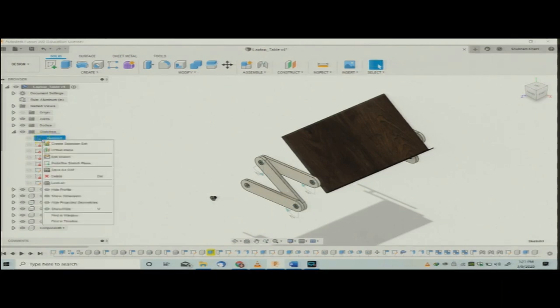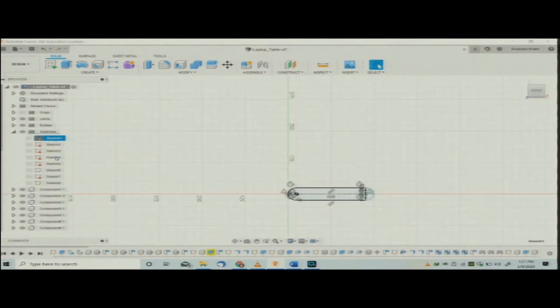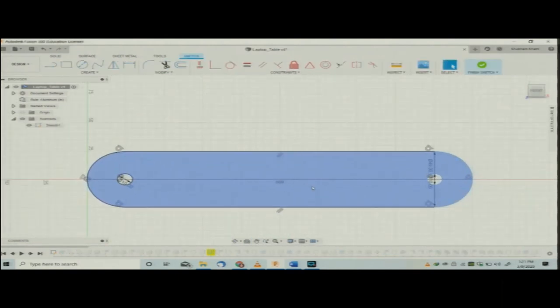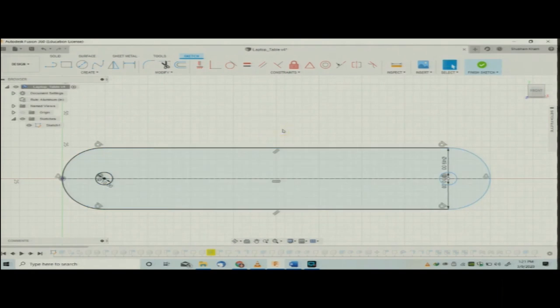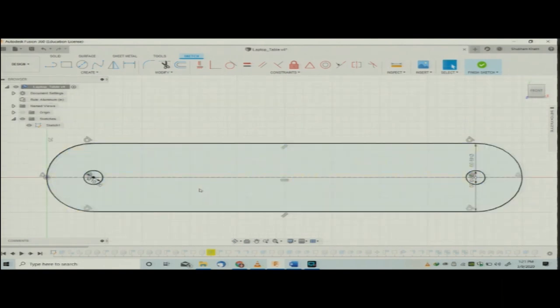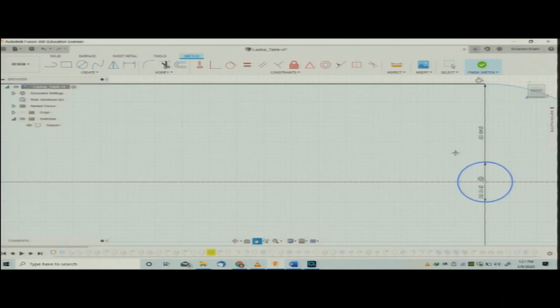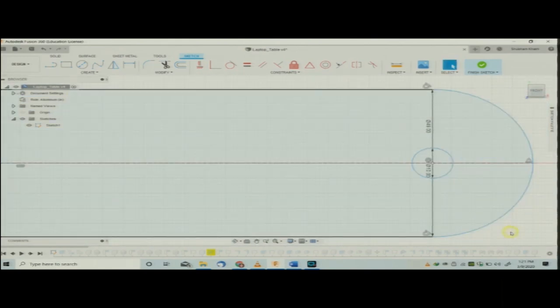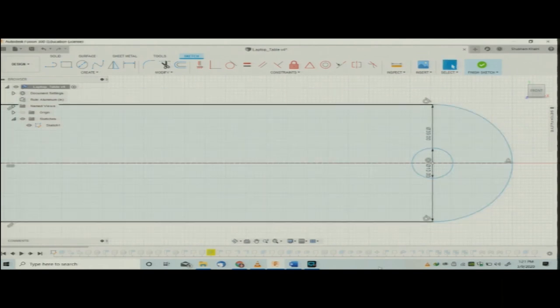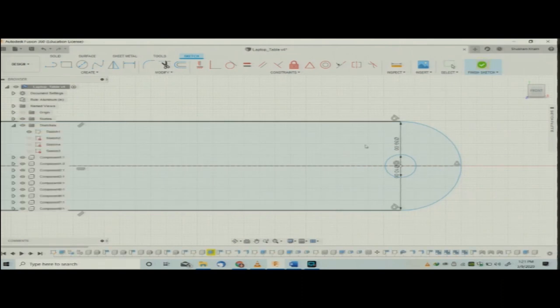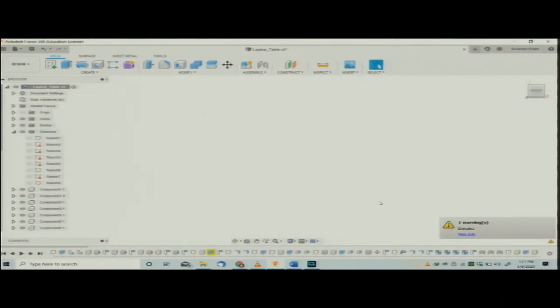So, let me try this. This is the sketch; right click on the sketch, edit sketch. So, we have the dimensions here. We are allowed to access the 2D sketch environment directly. Here the dimensions were already put as 49 mm dia and 10 mm dia. For this component, if we make any change here, for instance from 49 to 39, see, this dimension is changed. I am saving it. It will automatically reflect in our 3D geometry.